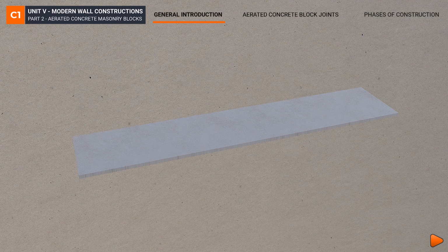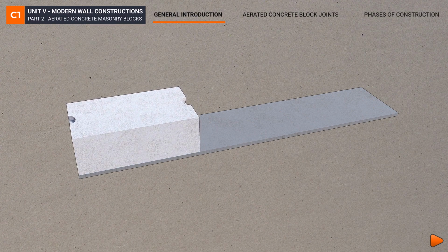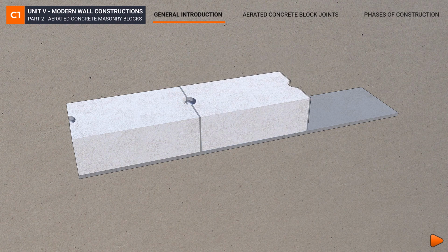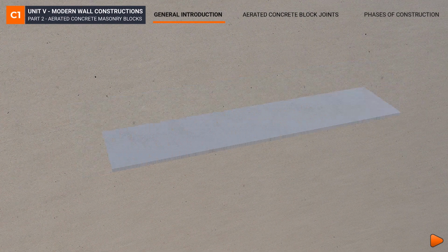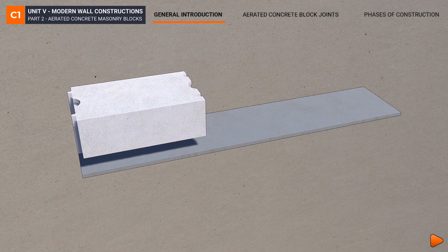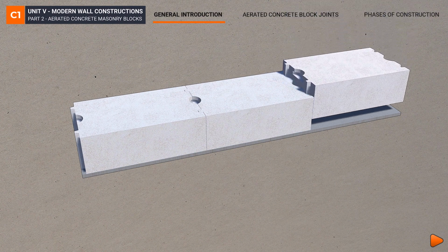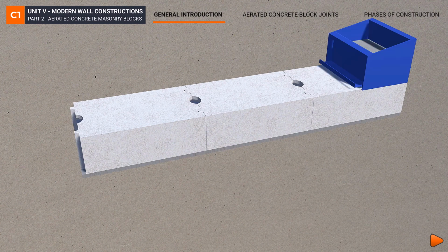The preceding information applies to grooved blocks, and mortar must be used for vertical gaps. However, the vertical joints of the grooved and tongue-and-groove blocks are already dry built. Furthermore, in this case, only thin bed masonry mortar can be used.